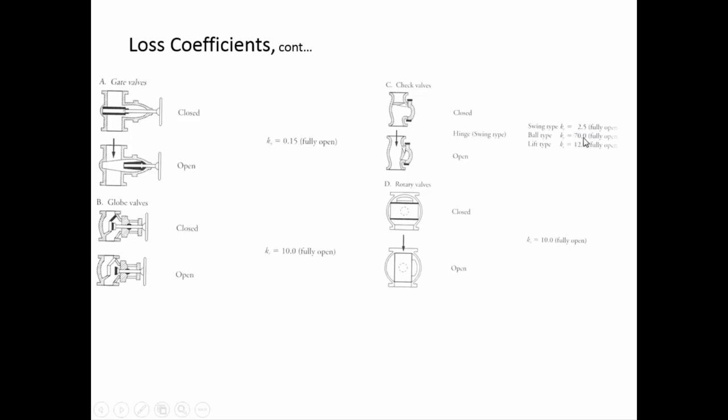And a ball valve is a little ball that, as the water is flowing with enough pressure, it pushes the ball out of the way, but when the pressure is too low, the ball will drop and cover the opening. But it's just that as water has to flow around that obstacle, it causes a lot of disturbance to the flow. You can look up these K values from the manufacturer specified tables, and we'll pull open an example of what a manufacturer K value table looks like.